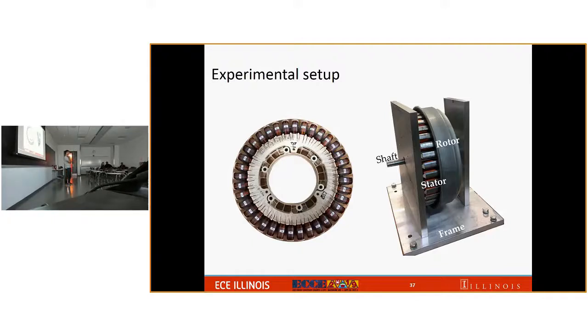So if you're having some go to passive rectifiers and some go to active, then I imagine at different points circumferentially around the motor, you'll be pulling different power. And that could create interesting thermal situations where one area gets more thermally stressed than others. Have you thought about that or how it would influence lifetime or anything? Yeah. So we are still in the process of designing a generator, and the thermal aspect will be considered in that phase of the project.